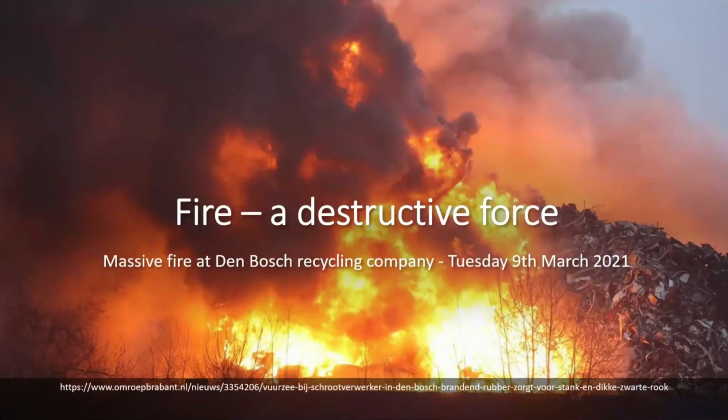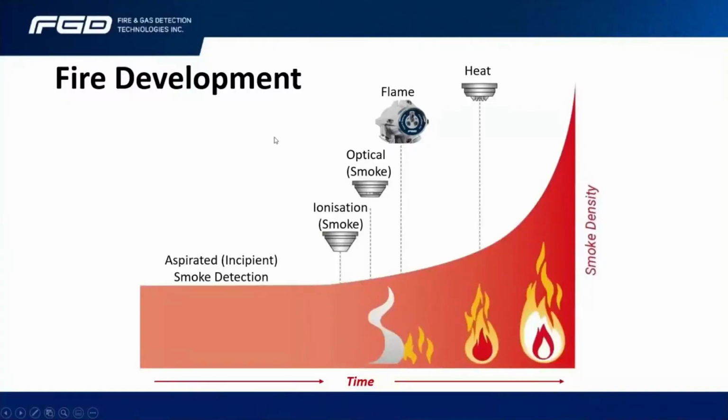And so the most important thing is, how do we stop a fire getting out of control? How do we provide something that detects fire at an early stage? And there in itself, I've used the word detect. So by understanding the growth phase of a fire itself, we can apply different types of fire detection technology. If we're looking at a very, very early stage, perhaps in a clean type environment like a data center, then we might use the aspirated type smoke detection system that would be linked directly into the control cabinet of each of those data packs themselves.